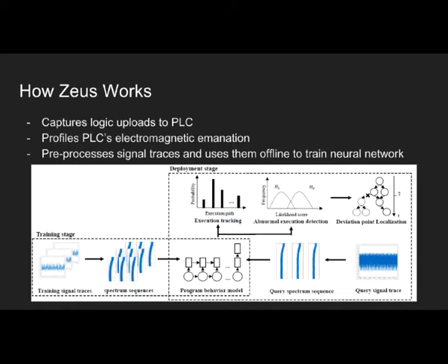depending upon the processors, there are some processors where there isn't a whole lot of instruction to instruction power variation. Let me say add and multiply and all. A typical RISC processor, all instructions are single cycle, and they look pretty much all the same. The power profile is reasonably flat. The reason the power profile varies is when something unusual happens, like going out to the memory. But on the other hand, complicated processors like Intel's, because we have microcode there as well, their instruction to instruction power can vary, right? So that's one part.